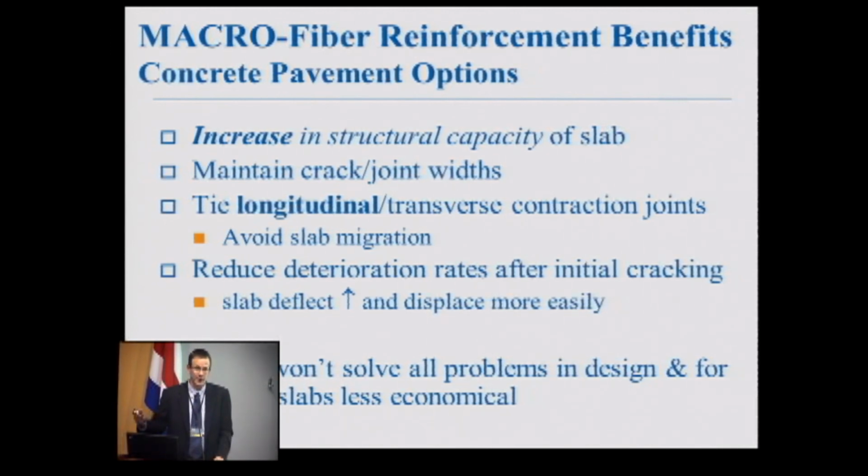So we're going to have cracking on our overlays because they're thin, and the fibers hold the cracks together. And generally, we can make those economical, but don't add fibers to everything because they won't be economical for every concrete pavement design.